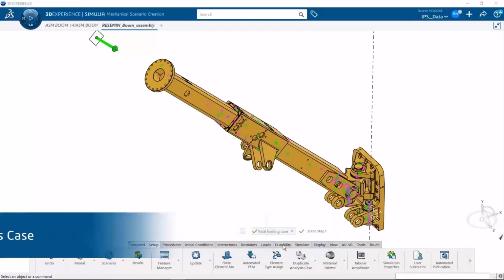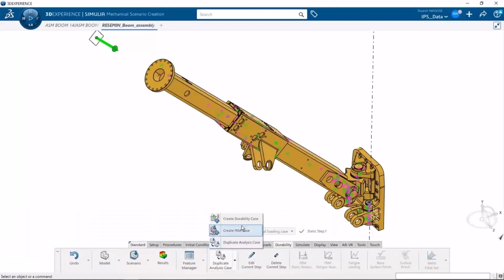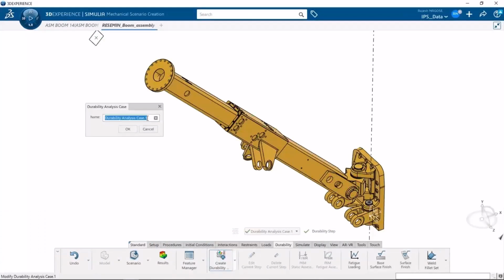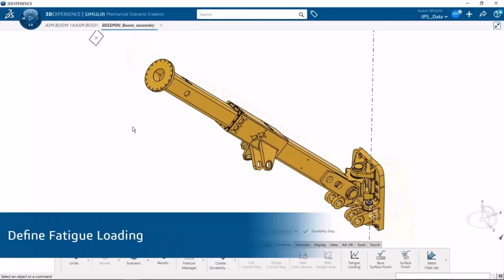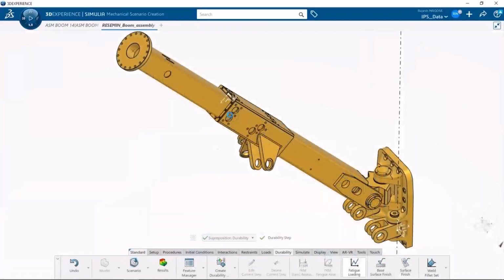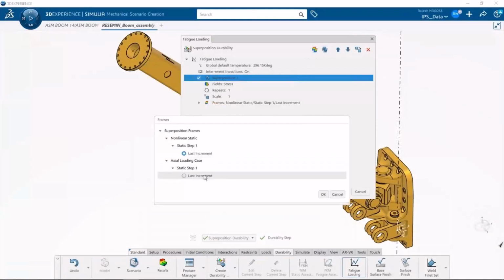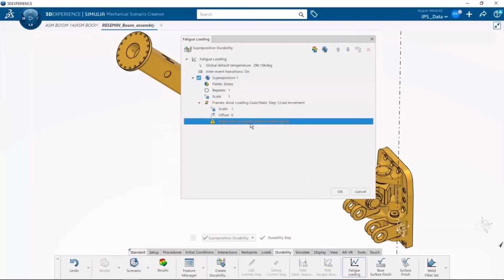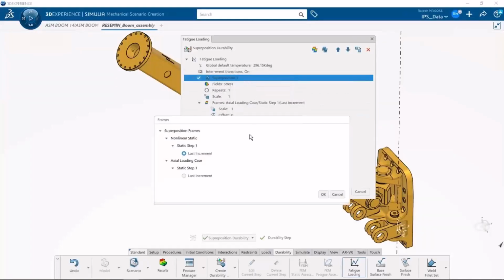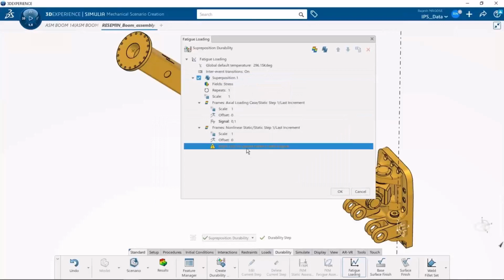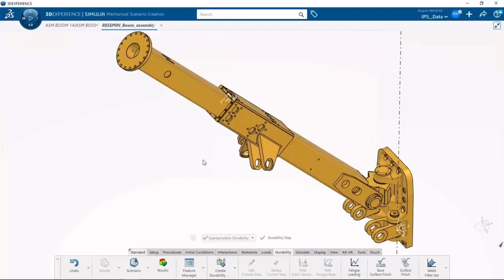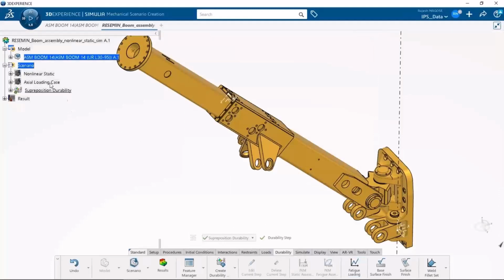So finally, I want to see the effect of both of those loading scenarios, both duplicated cases, in a fatigue study. And this is a fatigue life called a durability case, which handles both low and high cycle fatigue. And technically over in simulation, we only do high cycle fatigue. Mathematically, that is very different. Your lowest number in SOLIDWORKS simulation of cycles ought to be 1,000. Really, maybe 10,000, but 1,000 is the lowest you can go. Here we can do high stress, low cycle fatigue. And in this case, we're just setting up zero-based loading for these cases.